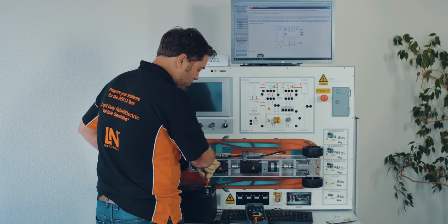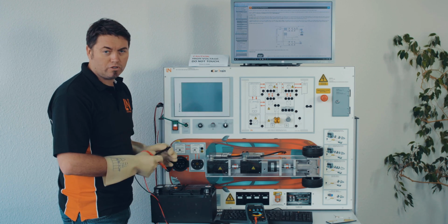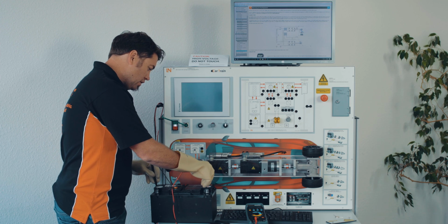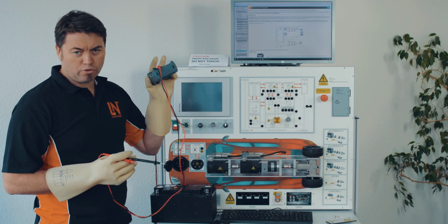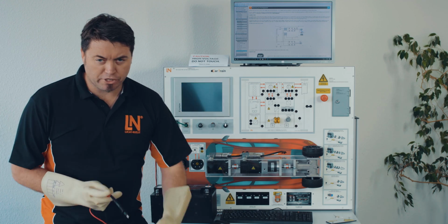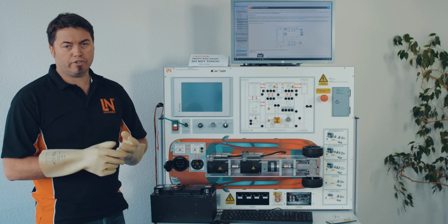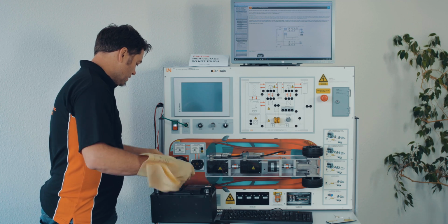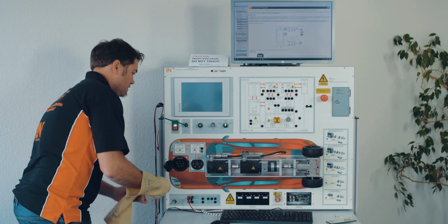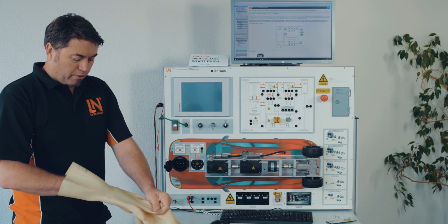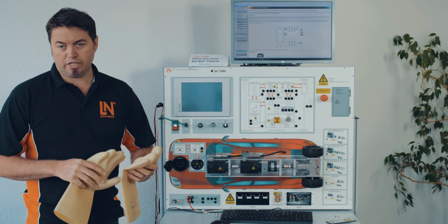and check to make sure that my measuring device is still working. That didn't blow it up measuring the high voltage. And yeah, I confirm that this battery now, this measuring device still works. At this point now, I'm satisfied that the vehicle is shut down, fully isolated, and I can now remove the gloves. Okay? Obviously at this point, the high voltage battery still contains high voltage, but the rest of the vehicle is safe.